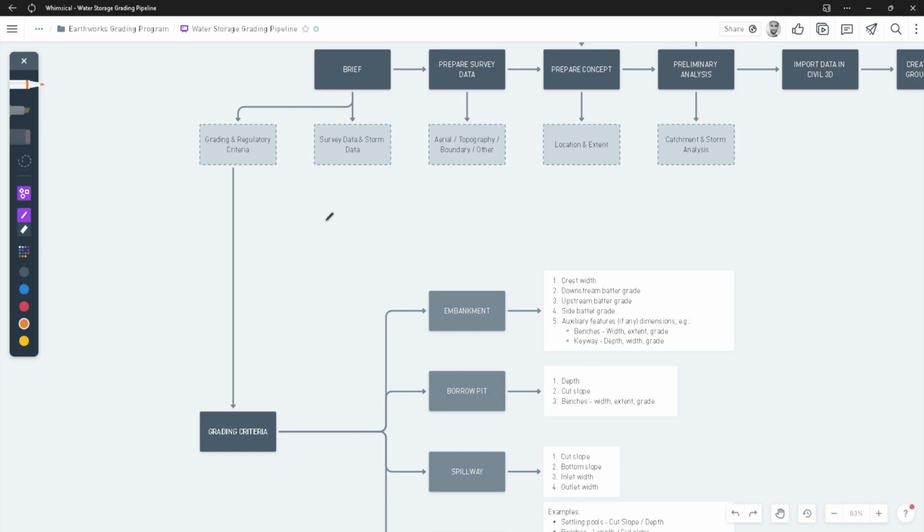So you really need good data, and I cannot tell you what exact accuracy that data should be, because it's going to vary depending on the project. But I would personally never work with data when it comes to grading that is less than 1 meter per pixel resolution, which already excludes much of the world, unfortunately, in terms of widely available data. So that would mean that a surveyor has to be hired usually to prepare that data, and that's very expensive.